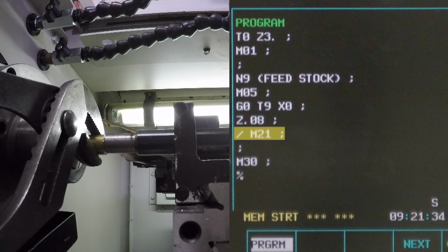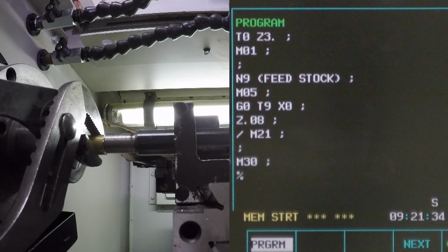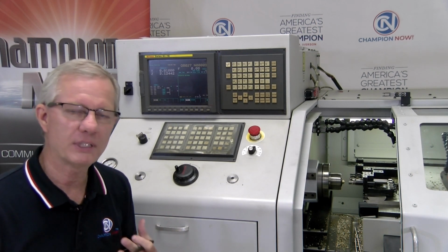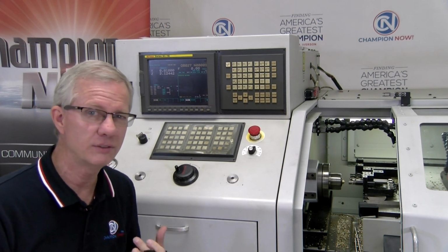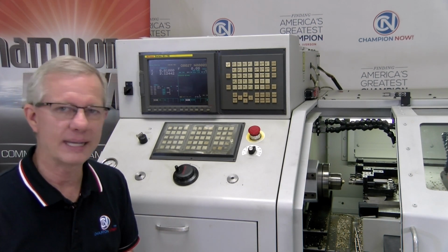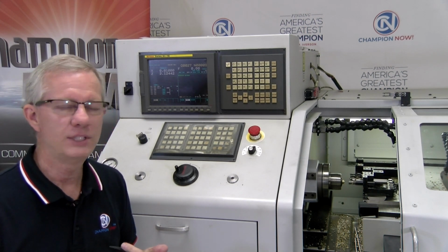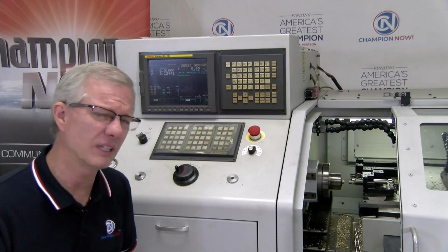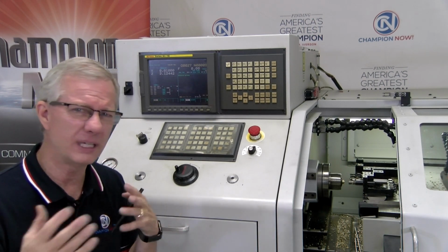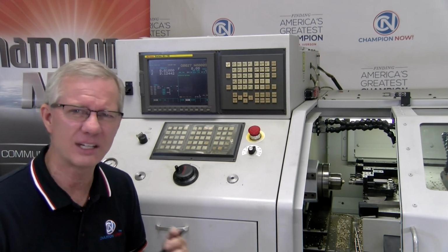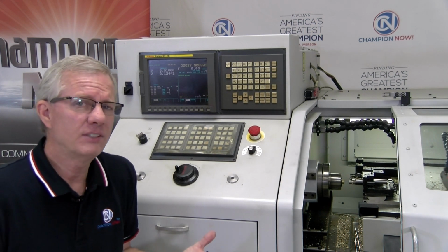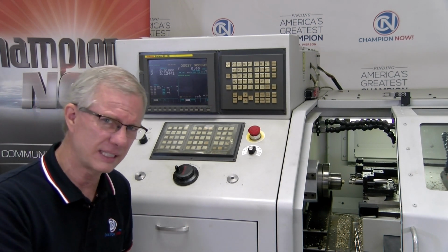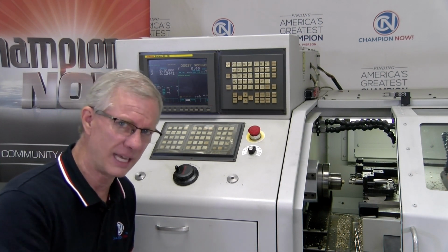So that's to try to demystify what CNC programming is. In summary, it's preparatory codes that are called G codes. Commands like S for spindle, T for turret station or tool. M codes that are miscellaneous functions like opening and closing things or turning things on and off. And then X and Z dimensions. Because it's a 2-axis machine, remember we said X is in diameter and Z is on length.